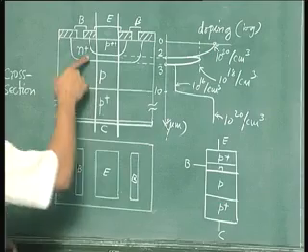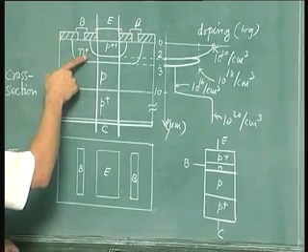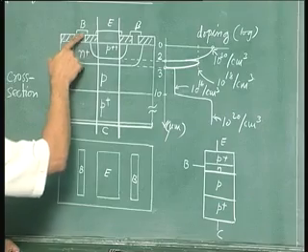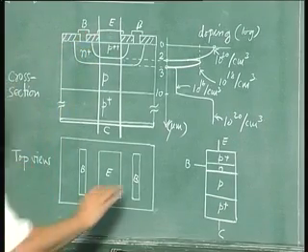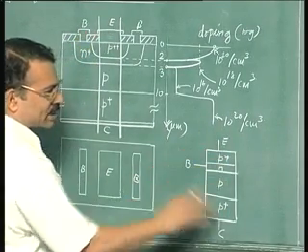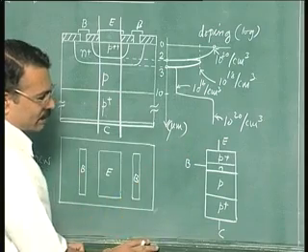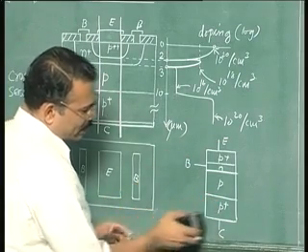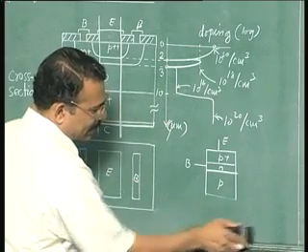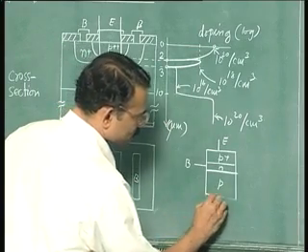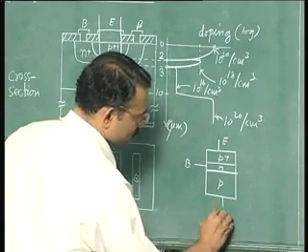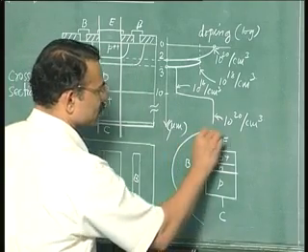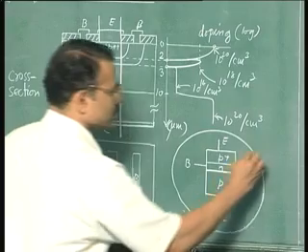As you can see here, in real life you cannot really connect the base contact here on the side as shown here. This base contact will be in the same plane as the emitter contact. But for the purpose of analysis we are showing an idealized structure with the base contact on the side. Further, what we will do is we will ignore this P plus layer and we will assume our collector contact is right there. So this will be our idealized structure of the PNP transistor.